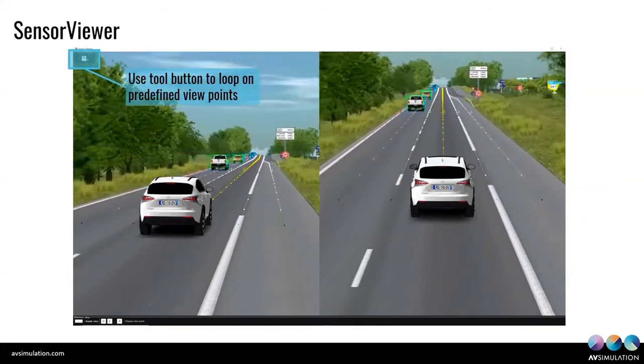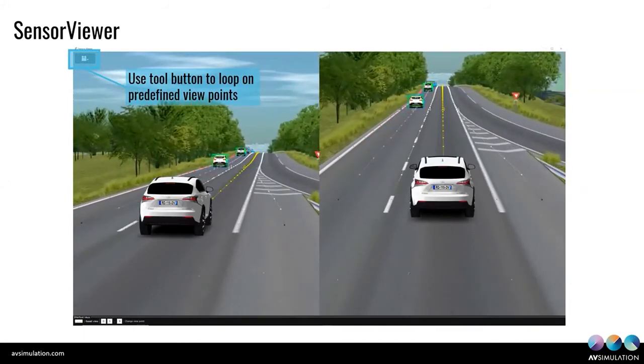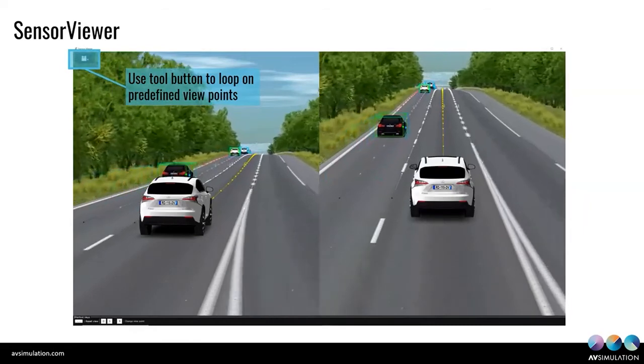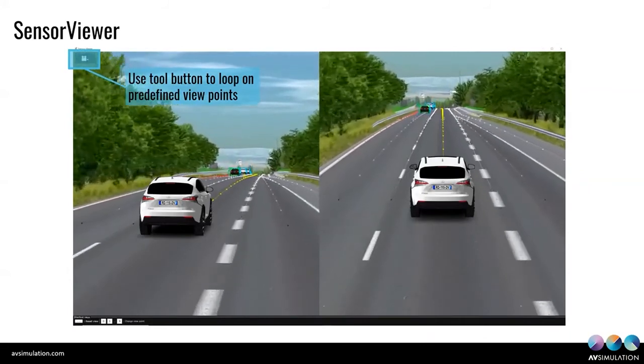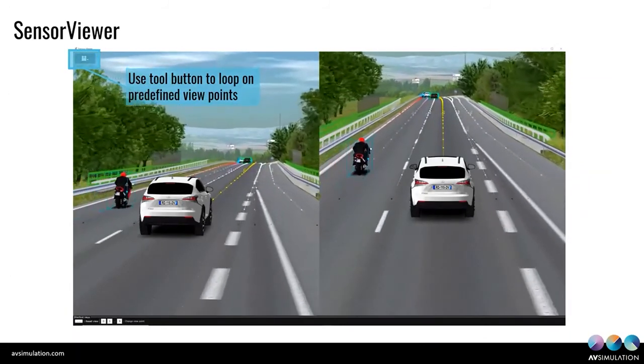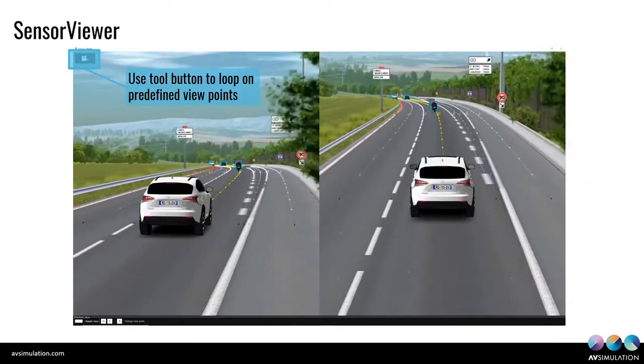It may come from a detection by a specific sensor, or from a fusion, so you can evaluate that your fusion data is incorrect, or from the decision, from the trajectory that has been computed, for example, or from the action, where the trajectory was good, but the system was not able to follow it. So it's very useful, because you can overlay a lot of information directly on top of the scene. It's very convenient to understand and to visualize the problems.